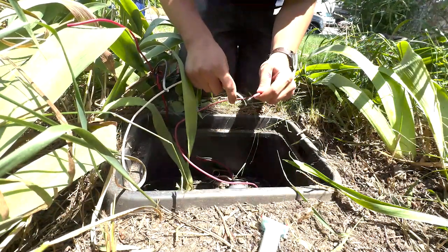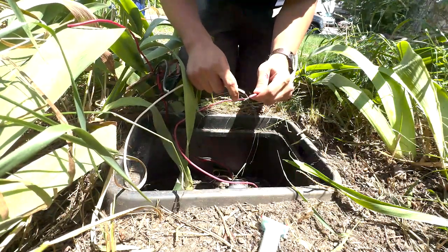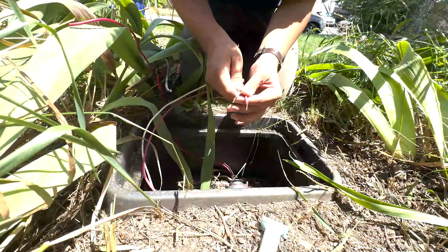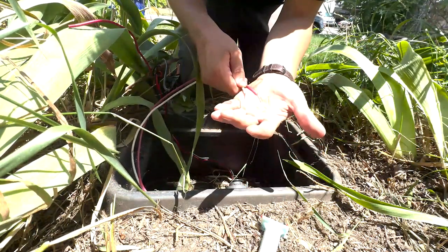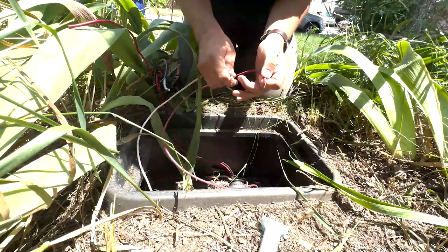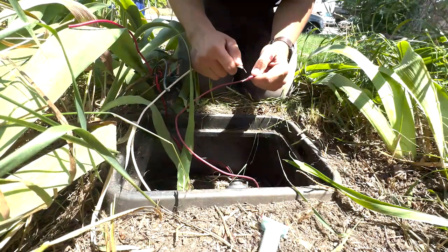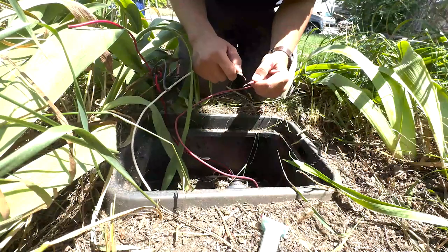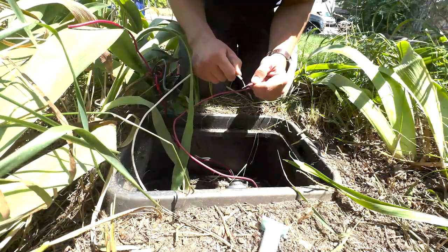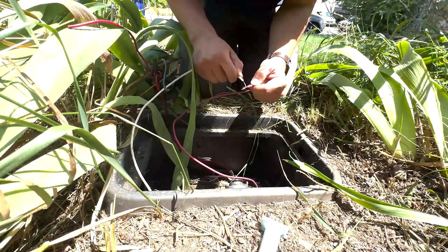Now, one thing that I check for every time that I'm diagnosing a flow loop is looking at the color of these wires. If these wires are copper colored, that's a wonderful sign. But if they've been corroded, they have a harder time carrying signal. So ensure that your wires are copper colored as you're tapping them together.